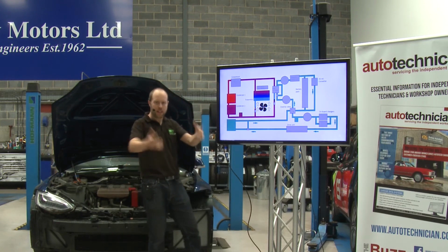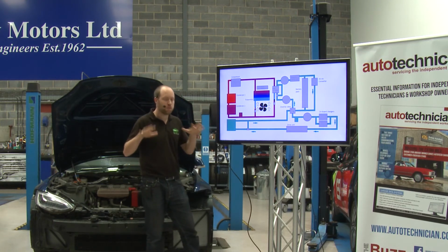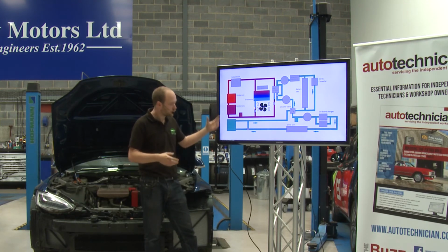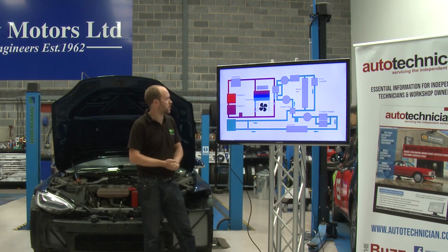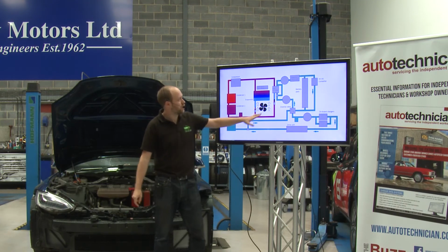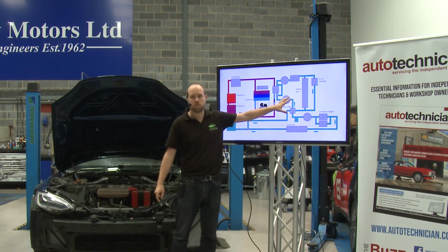We can have the radiator fans going full blast and everything, but the coldest we can possibly get that to is the same as the ambient temperature. And in, not so much here in the UK, but in some markets in the world, you know, the ambient temperature might be 40 or nearly 50 degrees, which is actually above our optimum battery pack temperature.